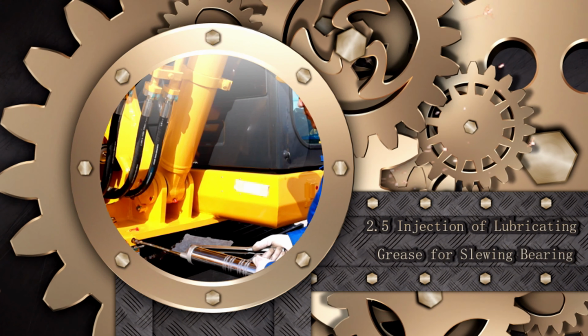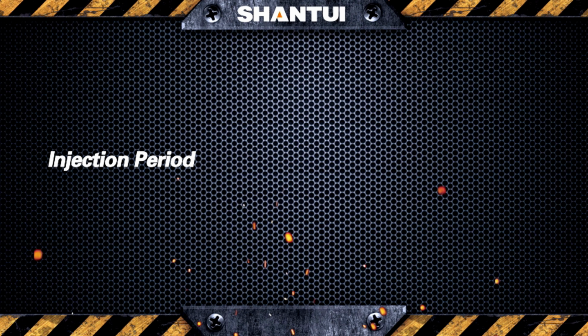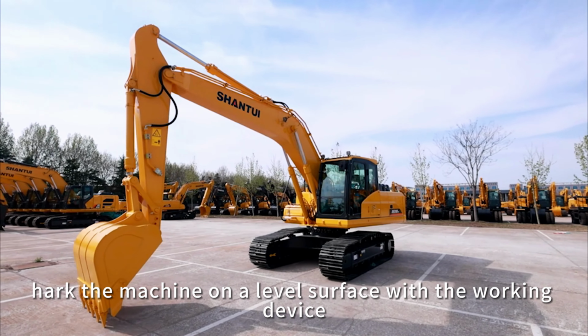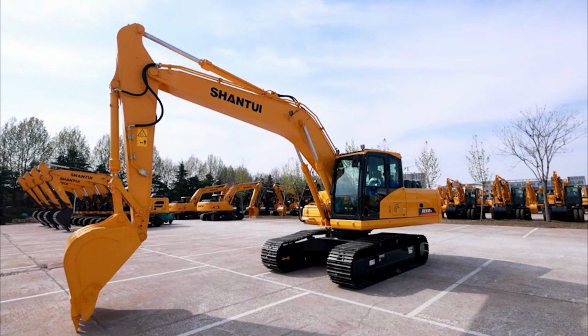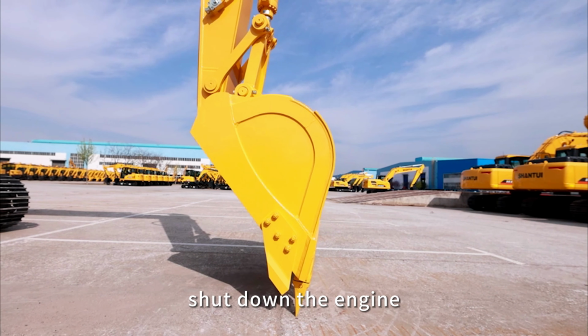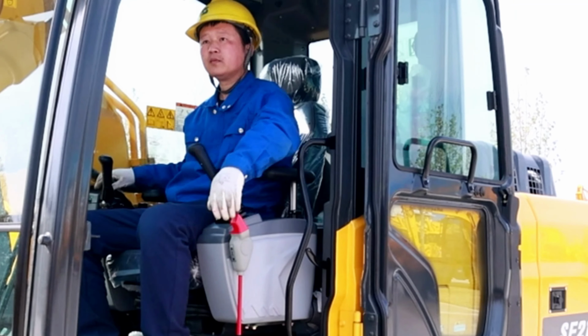Injection of lubricating grease for slewing bearing. Injection period: inject lubricating grease every 250 H. Steps: park the machine on a level surface with the working device facing forward. Lower the bucket to the ground. Shut down the engine. Lower the safety lock handle and lock the system.